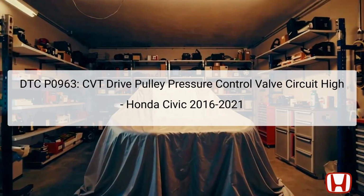DTC P0963 indicates an issue with the CVT drive pulley pressure control valve circuit in Honda Civic models from 2016 to 2021. This error signifies that the pressure control valve, which regulates hydraulic pressure in the continuously variable transmission, CVT, is malfunctioning, likely due to a high voltage or current in the circuit.